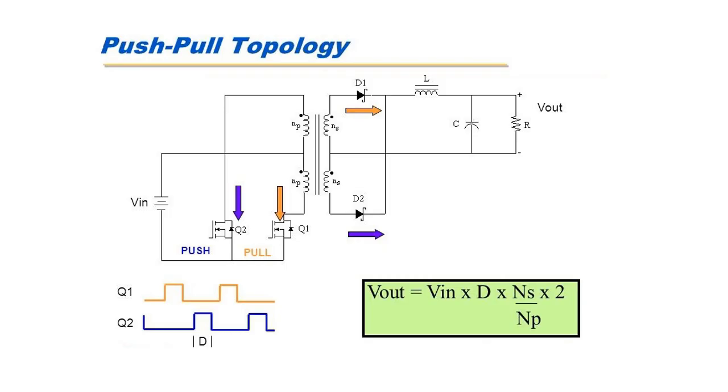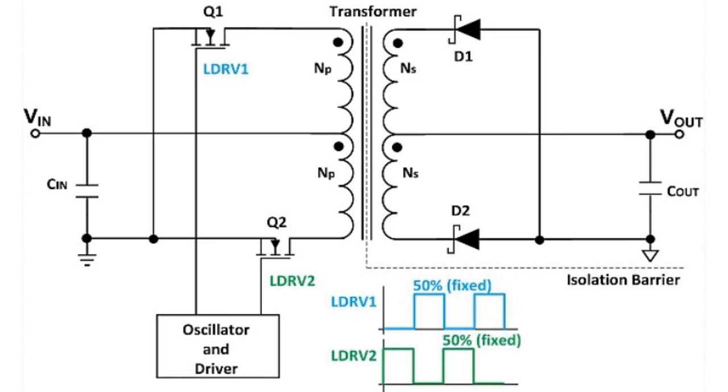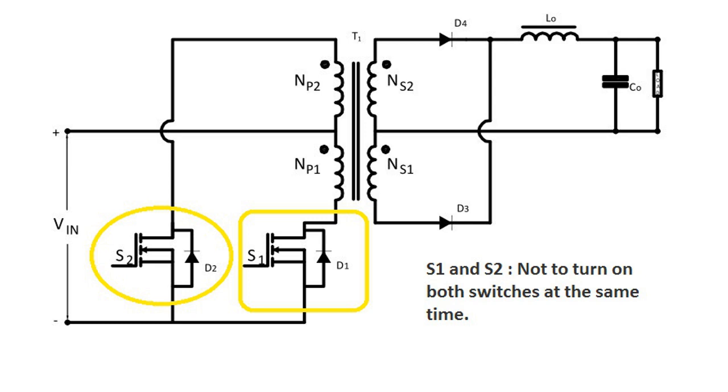Push-pull converter. The push-pull topology is essentially a forward converter with two primary windings used to create a dual drive winding. This utilizes the core of the transformer much more efficiently than the flyback or the forward converters. On the other hand, only half the copper is being used at a time, thereby increasing the copper losses significantly in a similar size transformer. For similar power levels, the push-pull converter will have smaller filters compared to the forward converter. However, the advantage that push-pull converters have over flyback and forward converters is that they can be scaled up to higher powers.